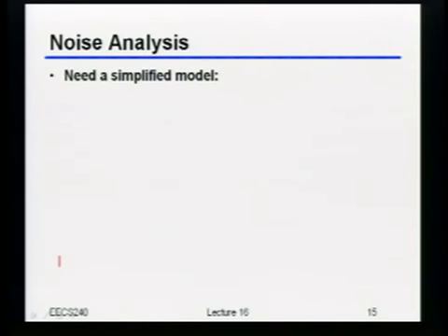So I'm going to go back to our very simple model for the two-stage amplifier, which looks like what we've been drawing multiple times already: essentially two common source stages. For now, let's not worry about the nulling resistor. Let's assume I can get a design that just looks like this to work the way I want. When I'm building this, I'm typically going to be using the amplifier in some sort of feedback loop, for example our capacitive feedback loop. So I'm going to assume that here as well.